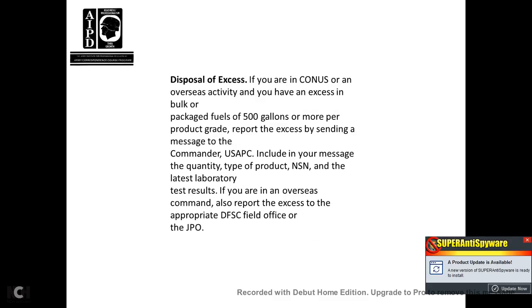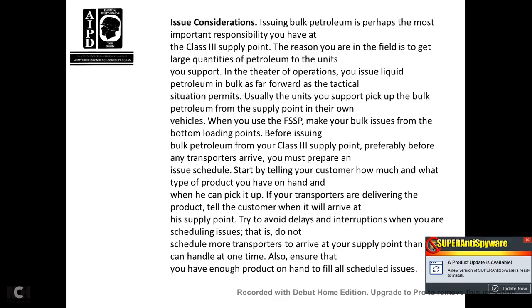Disposal of excess. If you are in CONUS or any overseas activity and you have an excess of bulk or packaged fuels of more than 500 gallons per product grade, report the excess by sending a message to the commander, U.S. Army Petroleum Center, including the quantity, type of the product, NSN, and the latest laboratory test results. If you are in an overseas command, also report the excess to the appropriate Defense Fuel Supply Center field office.